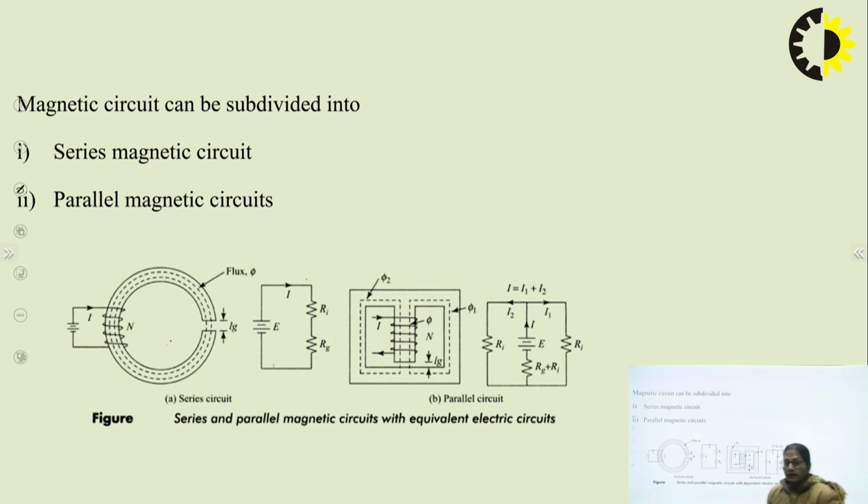A parallel magnetic circuit instead is having now three limbs, right? And on the central limb, the source is being wound. I mean, the MMF would be created in the central limb as the source is here. Say this is the total flux phi. Now, at this point, the total flux would be divided into two, phi 1 and phi 2.